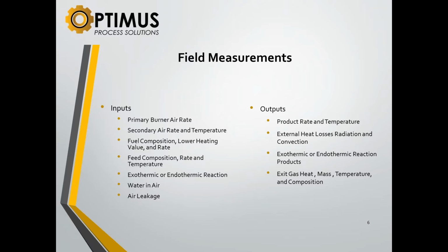Something we'll get into later, there's a lot of combustion air involved in that, and air has humidity, it's not dry, and that has an effect on your system. And these are all the stuff that goes into the system. And then if you have a lousy seal, you get a bunch of air leakage, which defeats the whole purpose of your burner.